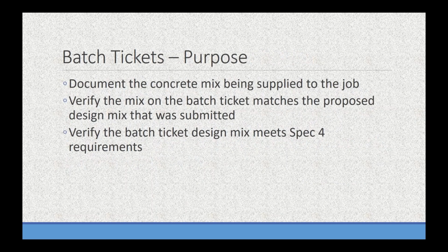So why is it important to keep batch tickets? Well, it's important to keep a batch ticket and actually look at it and check it, because we need to actually document the concrete mix that was supplied to the job. If we don't have a batch ticket to look at and reference and check, we have no documentation on what was actually delivered to the site and used for our project.